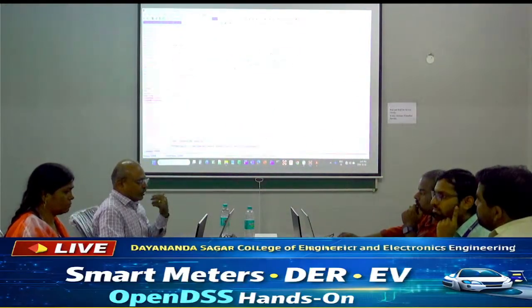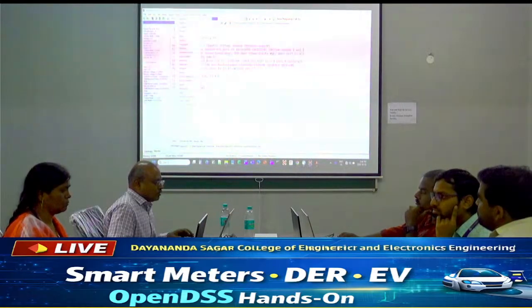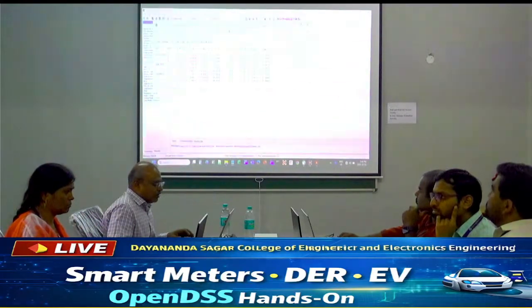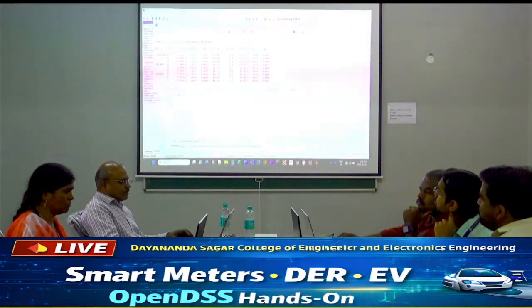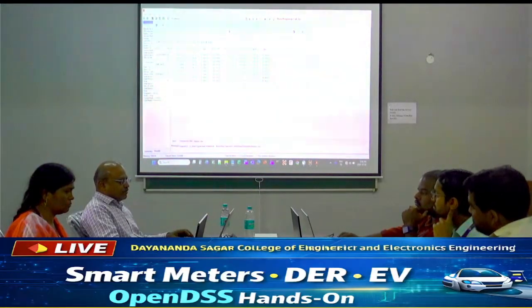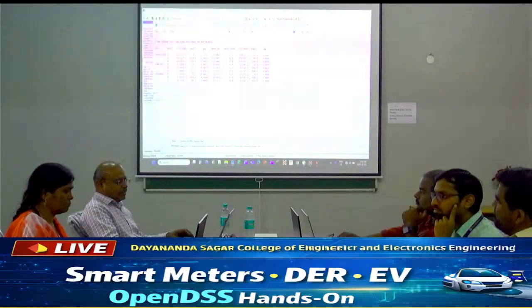Now if you say no, I want to get the whole thing out, you just say export voltages, and then you can tell what you want, right? Or show voltages, and if you say all the voltages you want to see, it will show all the voltages like source bus, the line and neutral voltages, angle, and the PU format, base case, everything.